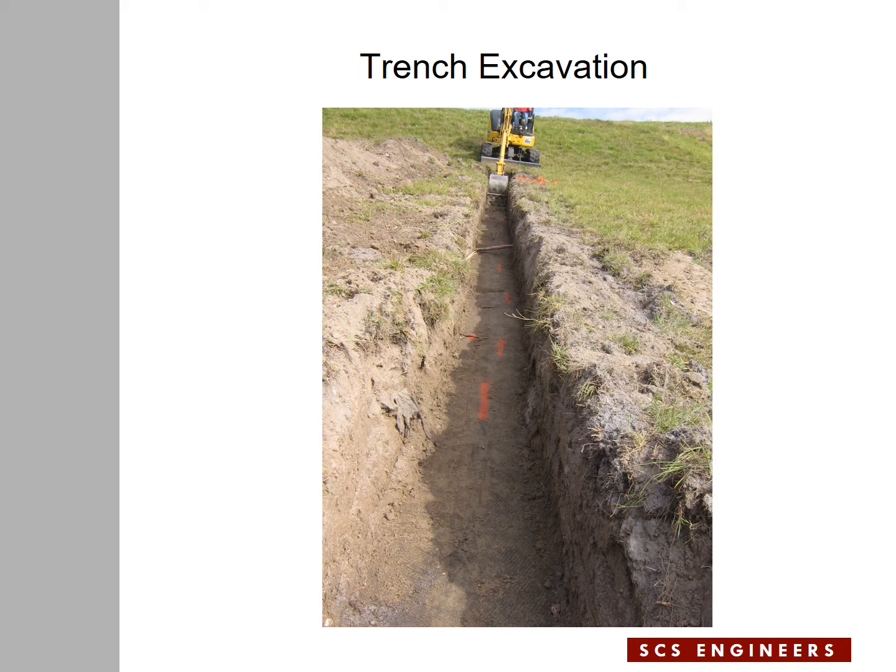In this slide, you see that the trench is excavated all the way down to the top of the composite, and the drain system sits directly on top of the composite. If water gets in the composite, the composite becomes saturated and water comes out of the composite, it will get into the perforated pipe and flow very rapidly to the bottom. That would prevent saturation of the soil above the composite.